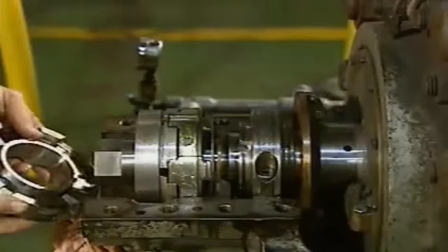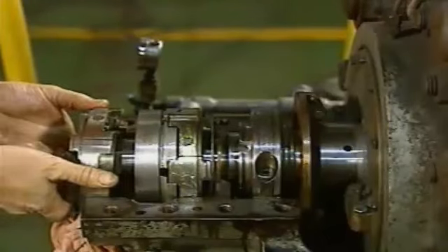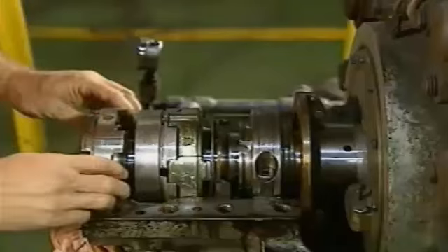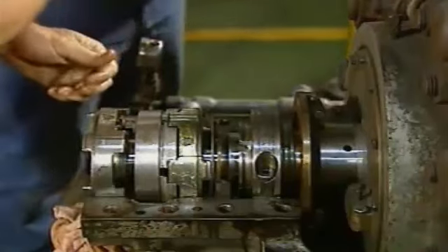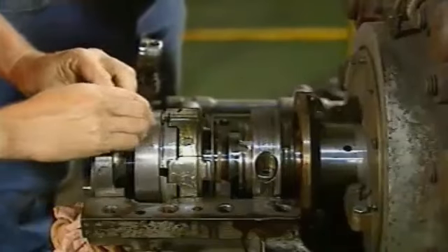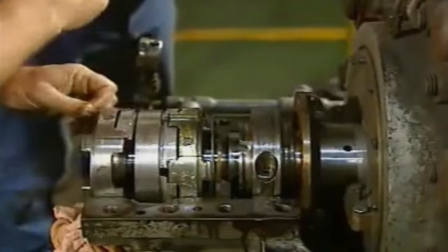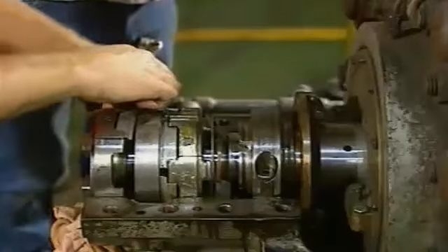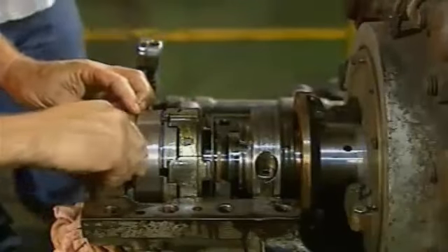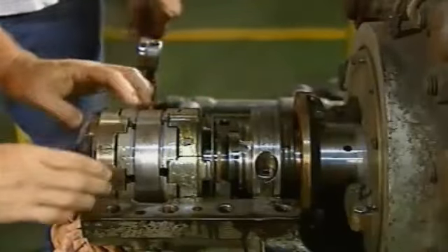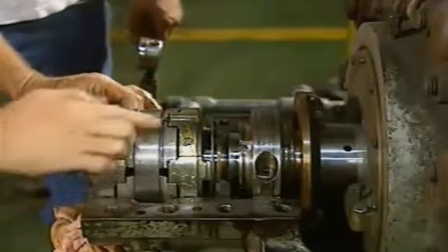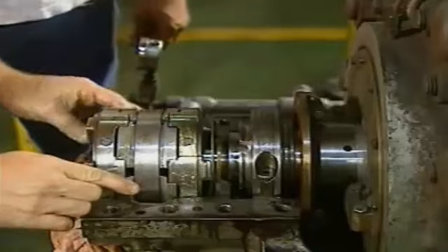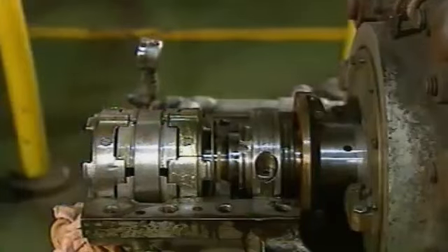Next, the outboard bearing support brackets and thrust shoes are installed. To make sure that the bearing components won't slide off the shaft, the mechanic carefully holds the support brackets in place as he installs the thrust shoes. When the outboard bearing is completely assembled, the mechanic rotates the outboard bearing until the locking pin groove is properly aligned with the groove on the inboard bearing.